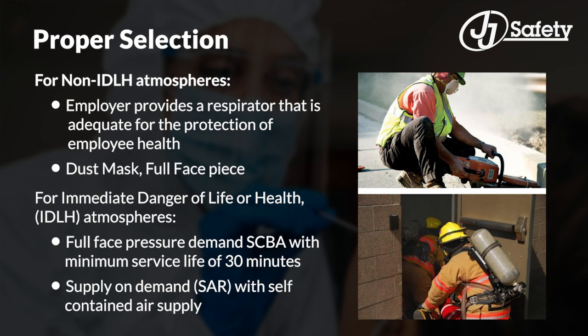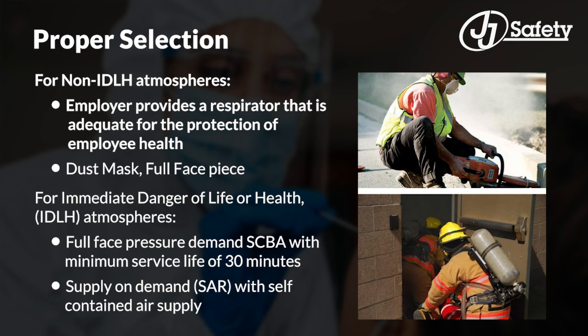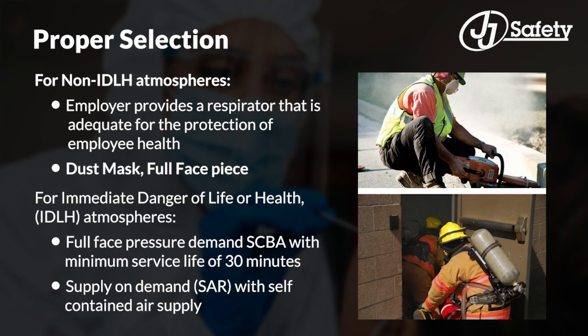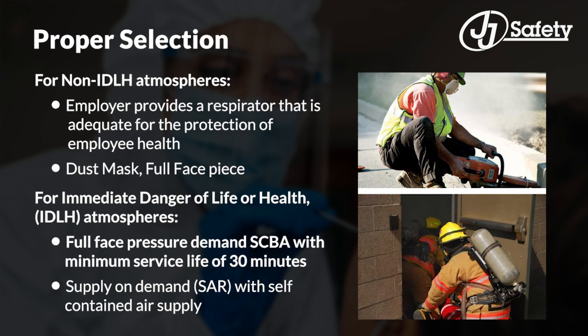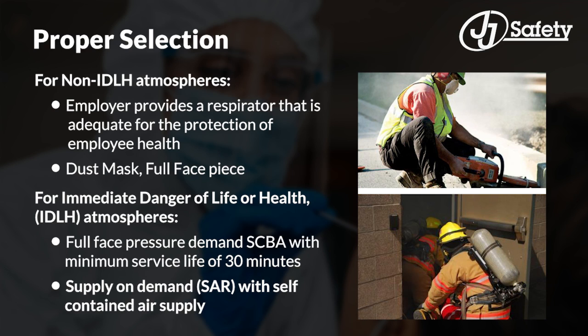For non-IDLH atmospheres, the employer provides a respirator that is adequate for the protection of employee health, such as a dust mask or full face piece. For immediate danger to life or health atmospheres, a full face pressure demand SCBA with a minimum service life of 30 minutes, supplied on demand with a self-contained air supply.